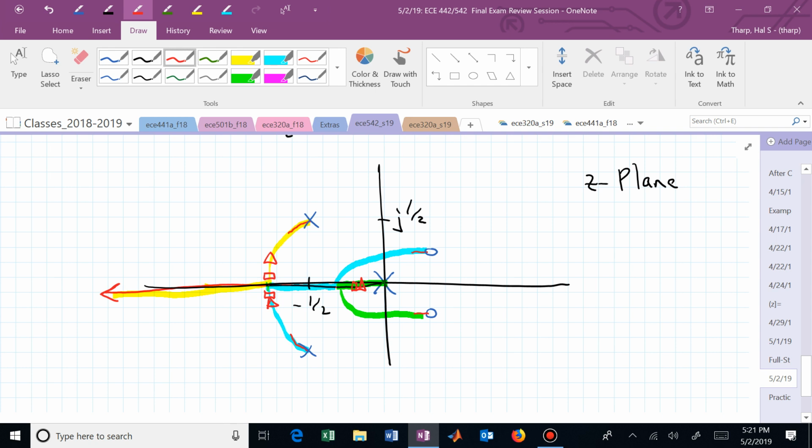Do you see that if I just graphed K, which you have a formula for K based on these poles and zeros, if you evaluated K from 0 out to -2, if this picture is true, you would see K hit a relative max, then it would start, what? Decreasing now to a relative min, and then it would just go unbounded. What would the other picture look like? So there we have a relative max followed by a relative min, and then it just goes monotonically big.